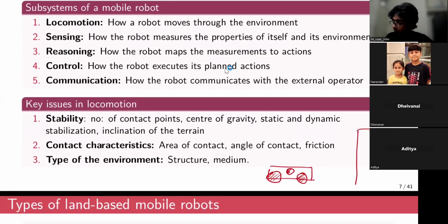If you have a robot that is a bit tall, like this, if you consider these to be the wheels, it has a very high center of gravity. If this sort of robot is moving in this direction and suddenly comes to a stop, there is a high probability that it will topple over because of this high center of gravity.